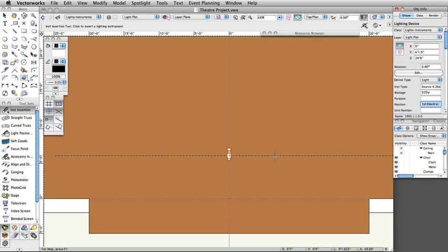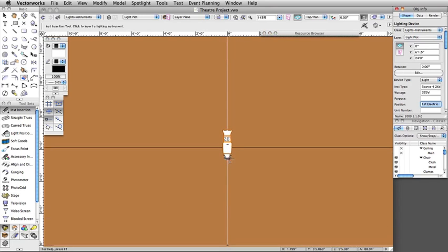The attributes for a lighting instrument can be modified through the Object Info palette, clicking the Edit button in the Object Info palette, or by double-clicking directly on the instrument. The unit number, channel, dimmer, circuit number, purpose, color, focus, wattage, beam/field angle, shutter depth/angle, and many more attributes can be modified. Lighting instruments can also be set to draw their beam in 2D and/or 3D. In this example, we will set a color and adjust the shutter.